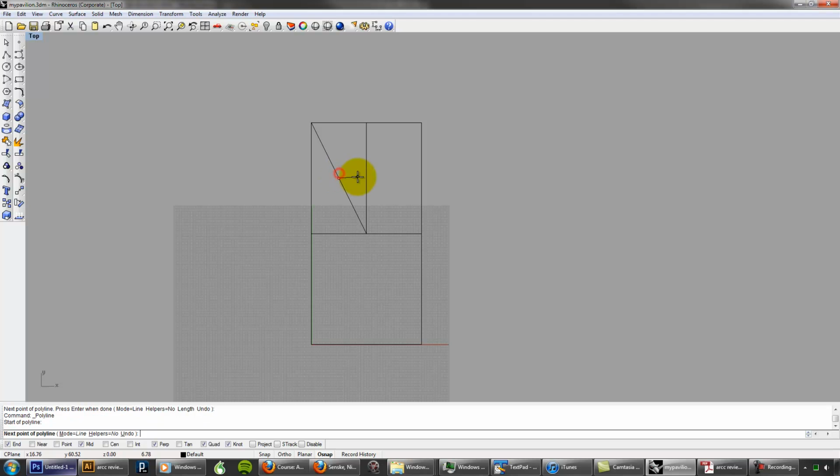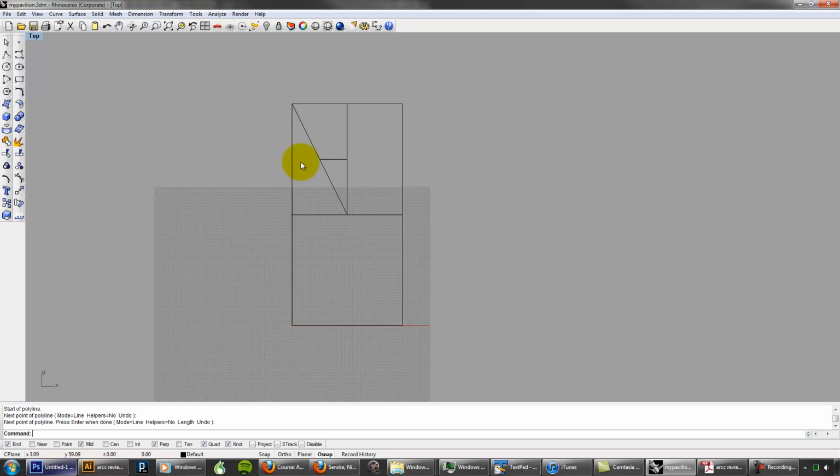And what I'm doing is I'm snapping. I have midpoint snaps turned on, perpendicular snaps turned on. I'm using the line tool. I click to make a line, I right click to stop the line, and it's basically snapping as I go. Okay, so I've got a series of pieces made, so I have kind of a center point.